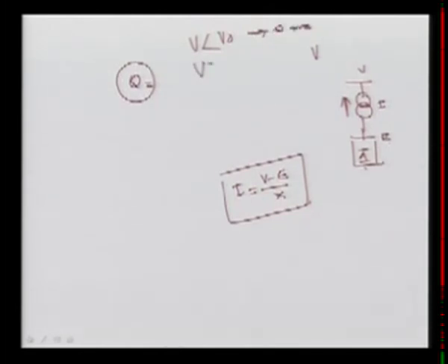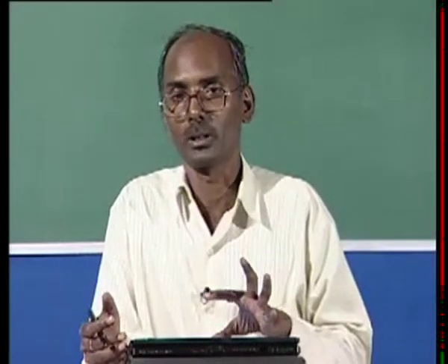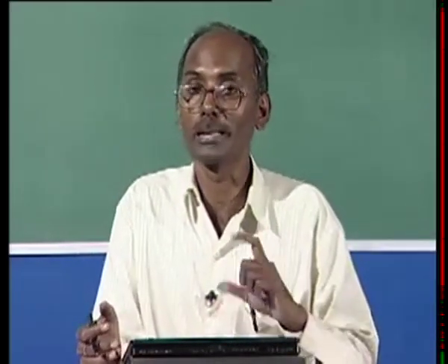When V is greater than V naught, they will absorb reactive power from the system to maintain the voltage. So these devices in the steady state will work like simple reactive power support devices, but their supplementary controllers can be used to improve the dynamic performance.